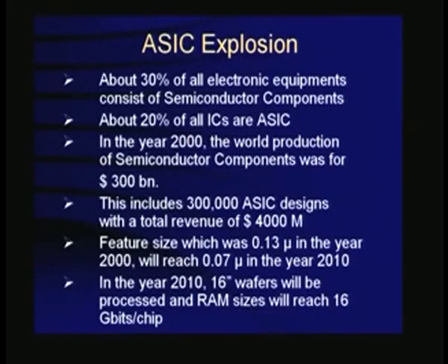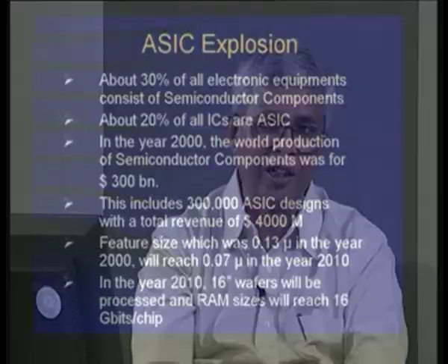We will not go into the actual definition of feature size here, but you have an idea. And that is 0.13 micron in 2000. In the year 2007, we are talking about 0.07 micron, which is talking about nanometers. 0.07 micron means 70 nanometers. 10 power minus 9 meters is a type of length, and this means the technology requires electron beam technology, electron beam lithography, molecular lithography, so many things, so many advances.